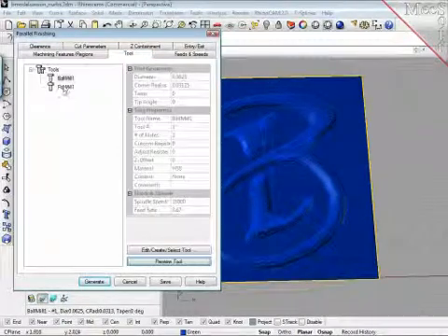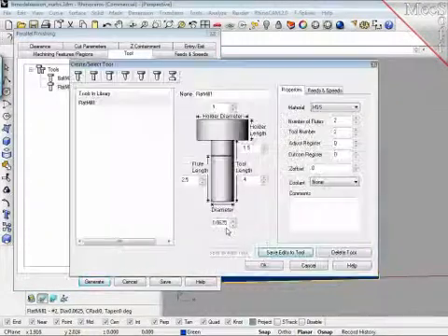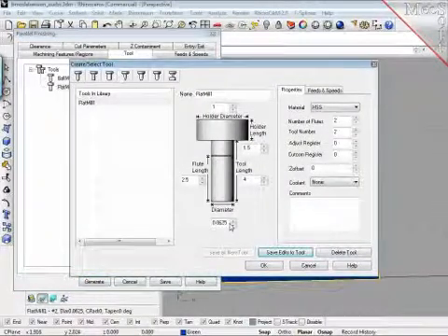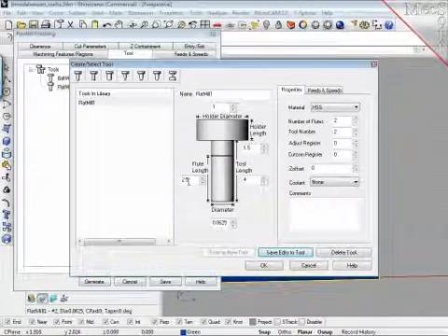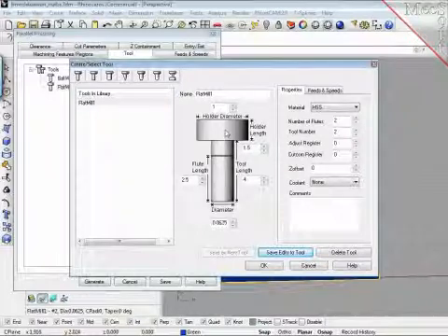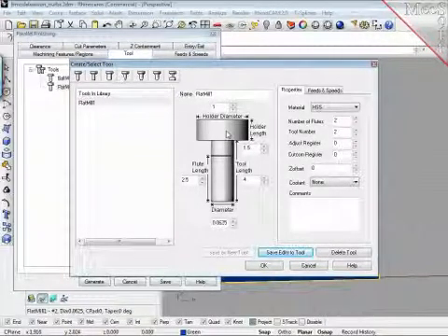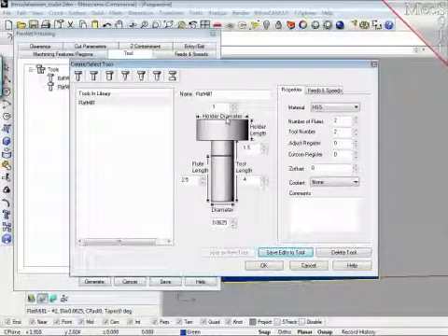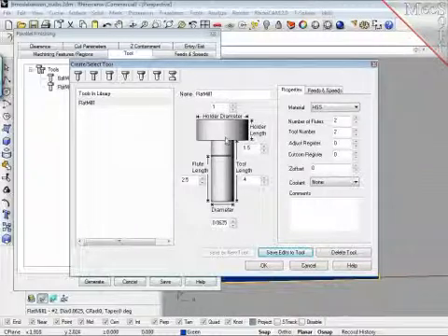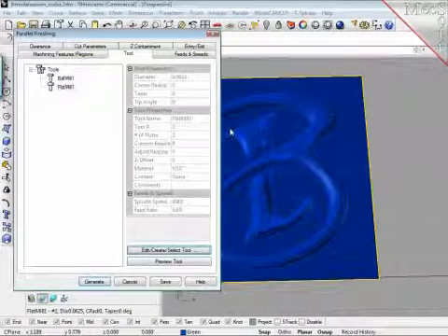Then I can define a tool, which is a 1/16 of an inch tool here, already prepared. Flute lengths, tool holder, diameters and stuff. RhinoCAM is able to provide information. If you cut very deep and very complex passes, then it will show you where your spindle would collide with existing geometry if you fill this in with meaningful parameters.